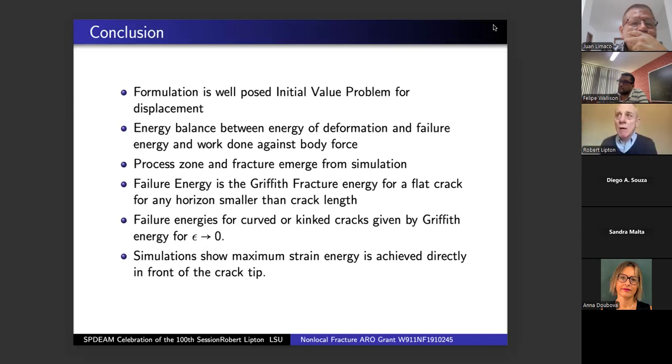And both of these are used right now on a very informal basis, okay? But in a very informal basis for attempting to, as you said, this Liberty ship, what they discovered is how to make sure no cracks will appear under a certain ensemble of loadings. And this was the major success of fracture mechanics from the 1930s on. It was very crude, but they had various ways. Basically, they just wouldn't even tolerate having a crack. And how do you do that?